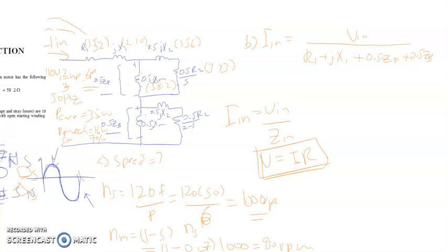V across here, which is 110 volt, divided by the overall impedance here. So you have to find the overall Thevenin impedance across the whole circuit. So we have here I stator equal to V in divided by the overall impedance of the system, which is R1 plus JX1 plus here the 0.5 of the forward impedance, half of it.